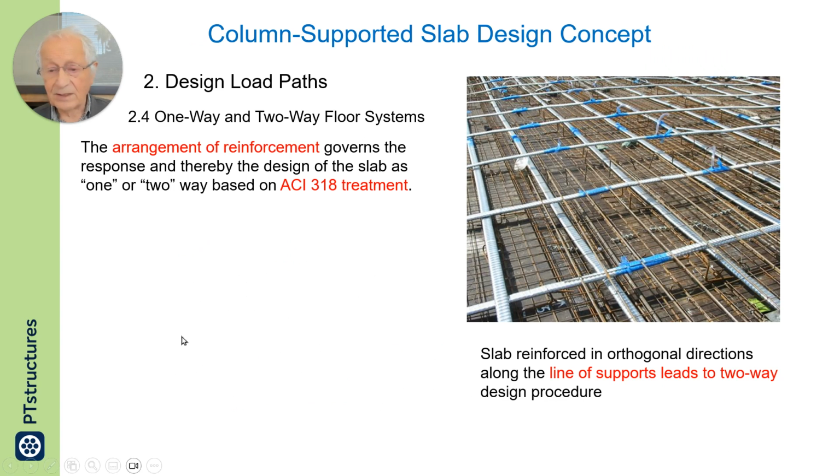Now here we have an arrangement, floor slab reinforced with bonded tendons, orthogonal in both directions, once in one direction and once in the other direction, or orthogonal to one another, which is a two-way system. The arrangement of reinforcement governs the response and thereby the design of the slab as one or two-way system.